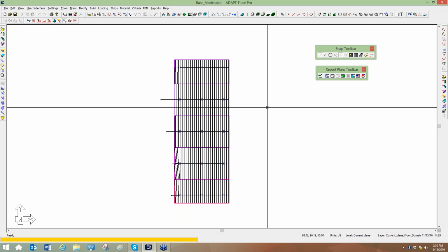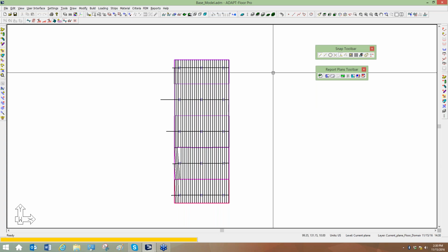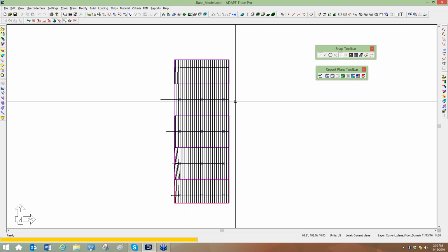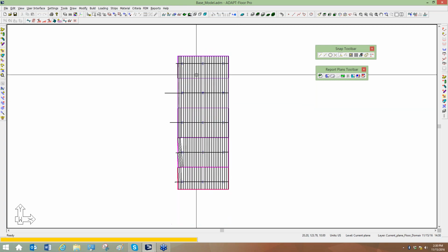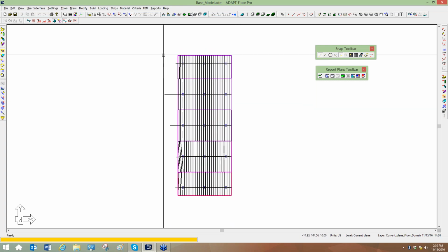In reality, most post-tension slabs, especially in the U.S., most designers that we see, or designs or models that we see, have the strips as full tributary for post-tensioning, and then obviously column and middle strip for a non-post-tensioned, just a regular two-way slab.